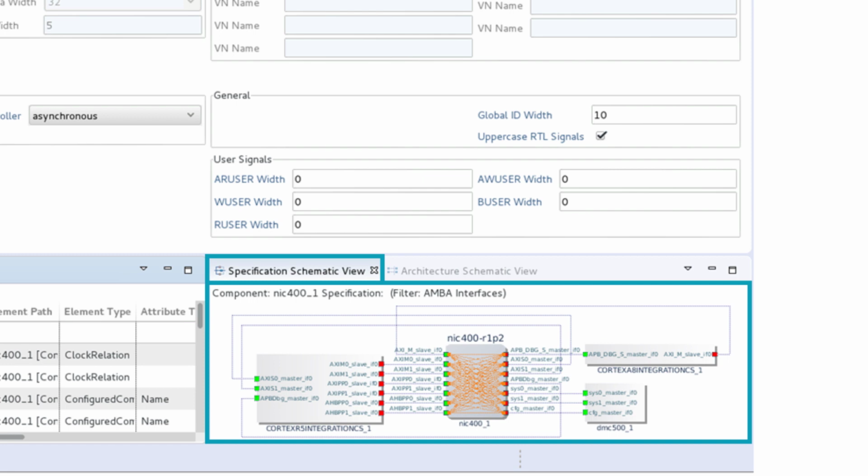If you use the built-in harvest flow to auto-capture the necessary interconnect-related interfaces from the IPexec descriptions of other IPs in your system, the tool will also display the boundary of those external IPs and will match those interfaces to the ones that it mirrored onto the NIC-400 boundary. Please note that these are not actual connections, as the tool will not integrate the created interconnect into your system. This is purely informational that can help you to see which are the interfaces belonging together in terms of integration.